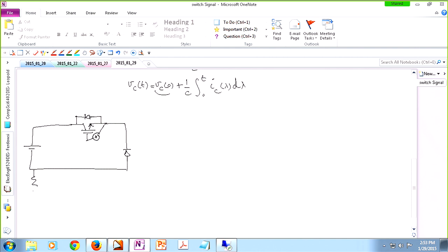So you would say, no problem, I will create a DC-DC converter here that takes our source. We already have a source. We don't need to use a second source. And then provides power to this pulsating source. So, for instance, you can say, my input voltage is 48, but I only need 5 volts over there, so I can use a buck converter for that DC-DC converter. But the problem is, your DC-DC converter has a ground over here, so it's going to give you another ground over here. That means as if you have actually grounded the source of your transistor, and that's not what you want to do basically.